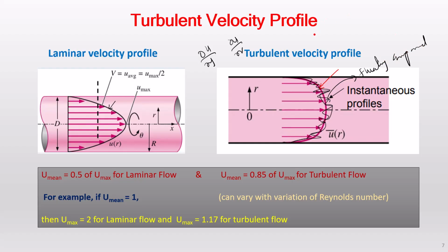Okay. So now I can put my u as a function of t, that is the instantaneous velocity profile, equal to the u bar, u average, and the u dash. So this is the average velocity over here, and any change that we are modeling from the mean velocity u bar definitely is not a constant value. But when we solve the problem using the RANS or the eddy viscosity models that we usually use for CFD, like k epsilon, k omega, these models assume that this change is constant.